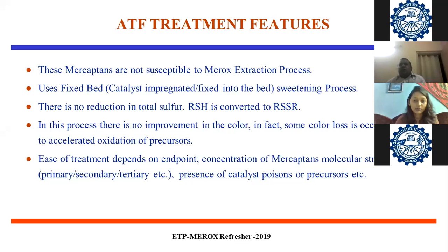Water has a color code of plus 30, highly transparent and crystal clear. The standard for ATF color has to be greater than or equal to plus 15. If it is less than that, it indicates that impurities are present in the ATF, which is rejected by the Government of India guidelines, because it is more prone to accidents in the civil aviation sector. So the color must be greater than or equal to plus 15.